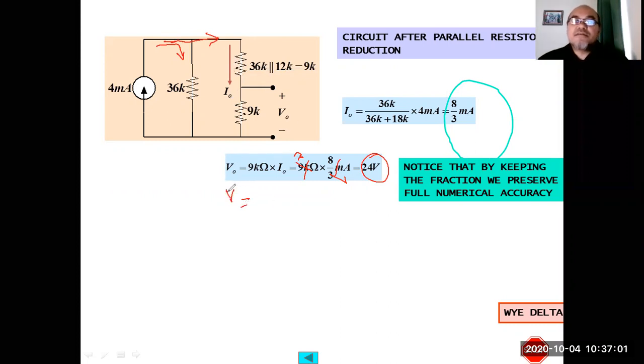Yeah, V equals to IR. Otherwise, we could of course also use directly voltage divider. How to use voltage divider formula? But it is similar. Basically, we need to know the voltage here, yeah, the voltage here across this. To know the voltage here, so alternatively, we can first calculate the whole equivalent resistance from the first branch, yeah, RS we obtain 9K plus 9K ohm, so equal to 18 kilo ohm.